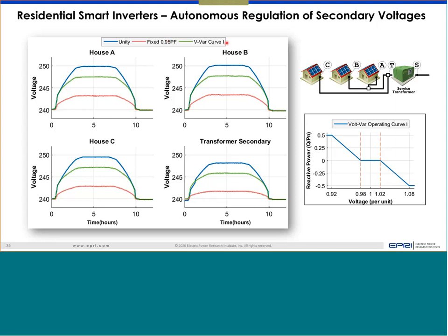When it was volt-var 1, which has a 2% dead band, it was not doing anything until voltage exceeded 1.02. So remember that part, that it only started absorbing var when it crossed 1.02, and since it may not have reached all the way to 1.08, it did not absorb the maximum var it can absorb. Maybe it was operating mostly in this part, maybe up to 1.04, 1.05, I don't know percentage-wise what will happen.